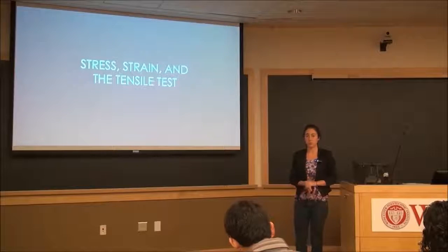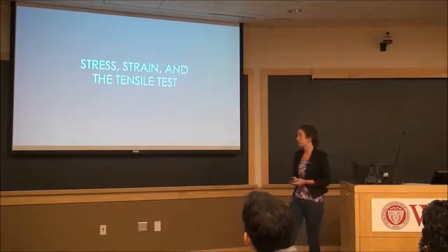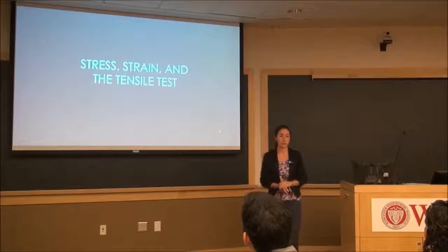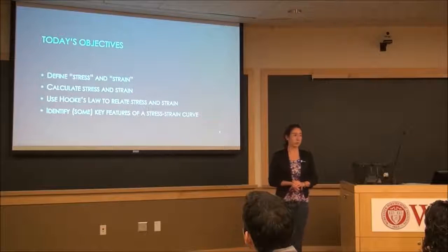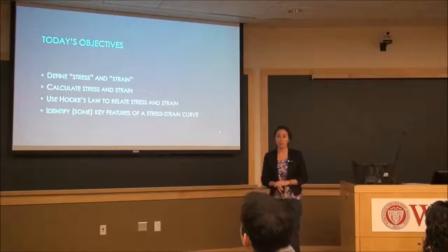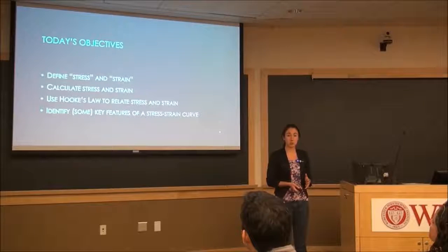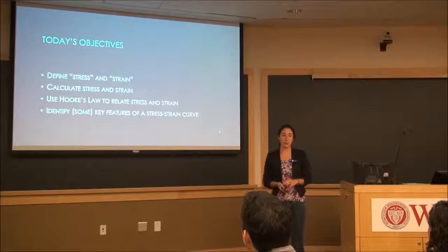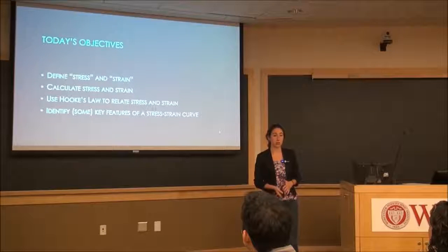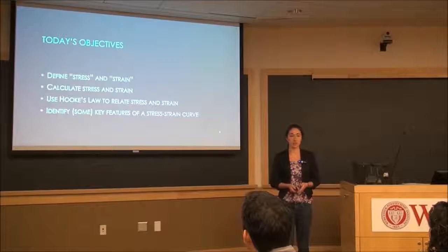Today we're going to start a new topic, mechanical properties, and we're going to start with the concepts of stress and strain, and we'll learn a little bit about the tensile test. By the end of today's lecture, you should be able to define the concepts of stress and strain, be able to calculate those values. You'll learn about Hooke's law, and you'll be able to use that to relate the concepts of stress and strain to each other, and you will be able to identify some of the key features on a stress-strain curve, which is generated from a tensile test.